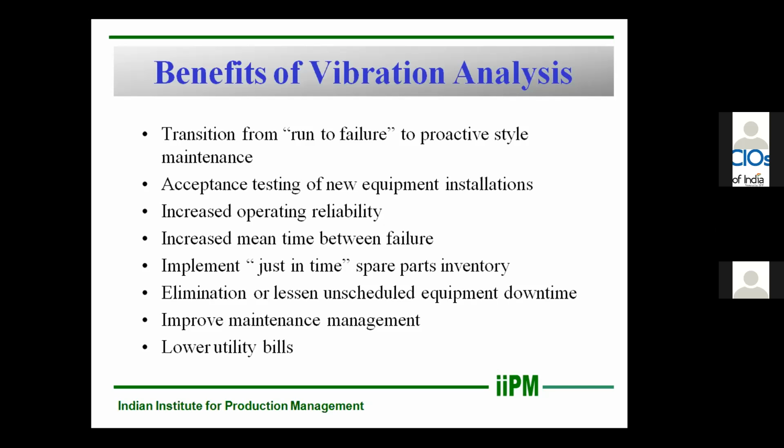Then acceptance testing of new equipment installation. Here vibration analysis plays a very major part. Suppose you install one new machine, and you want to check after commissioning whether my machine is operating in a normal condition or not. It can be done through vibration analysis because we have certain ISO standards. With that we can compare whether my machine is in normal condition, and after that I can tell the industry, yes it is okay, now you can run your machine.